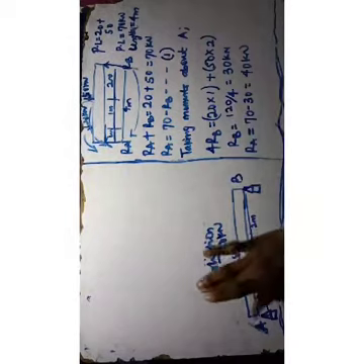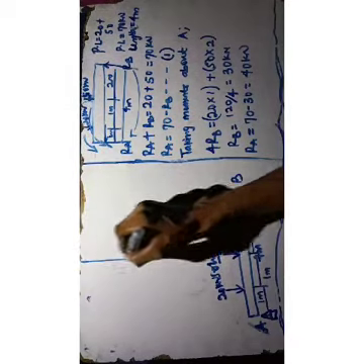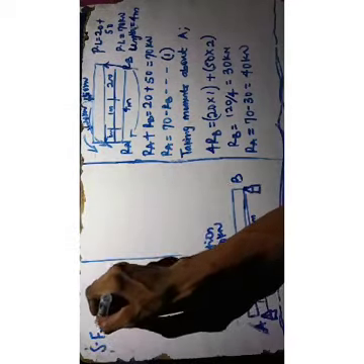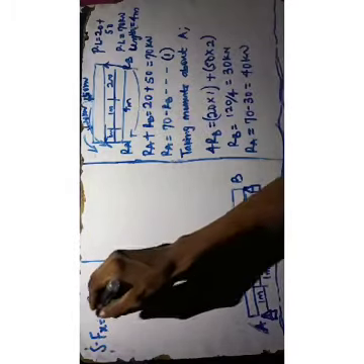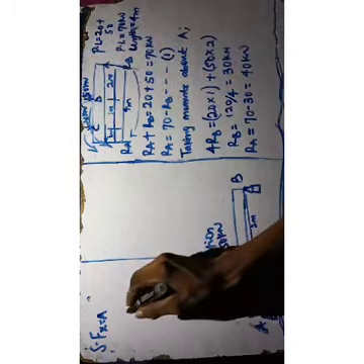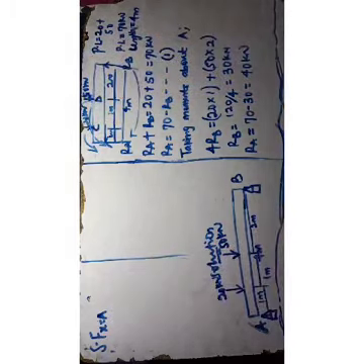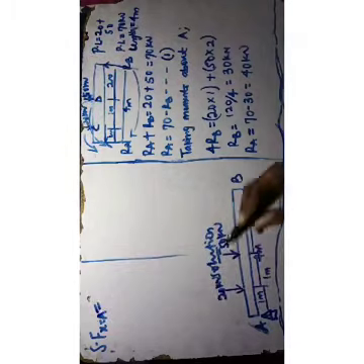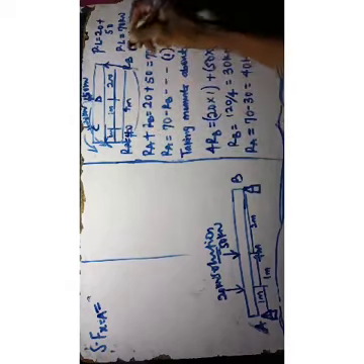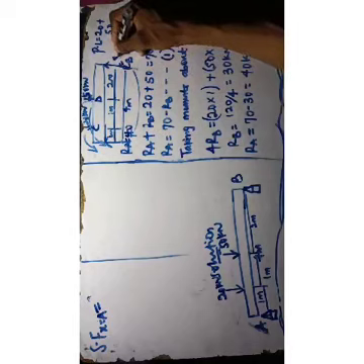So for shear force, I'm going to solve both at once. Okay, so for shear force at x equal to A. So let's say it is point A, point B, point C, point D. So at x equal to point A, the shear force will be equal to what? The RA, right? And we've gotten our RA as 40 and our RB as 30.